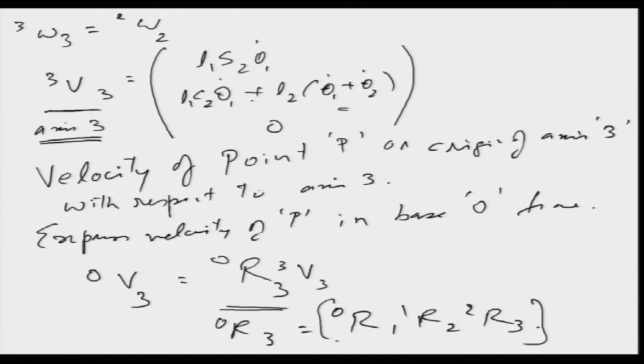Okay. So, next, we know how to get angular velocities and linear velocities. Now, what we need to look at is to move forward and see what the joint torques and the equation of motion are. What we mean by that is, we have seen the force propagation from the top, the forces come down, the velocities move from the base link to the forward link.